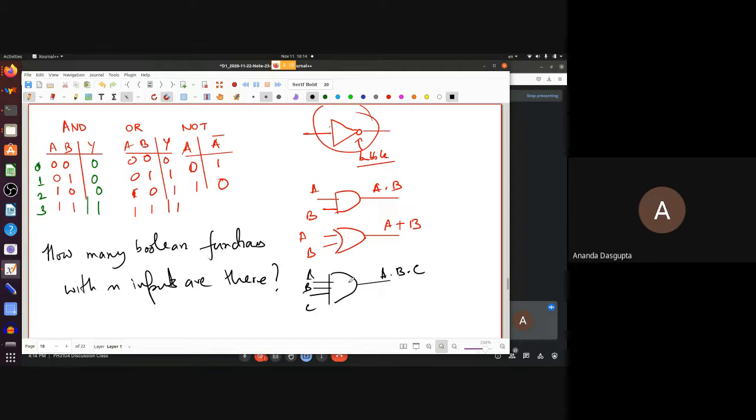The answer to that, of course, can't be 0 because you can see 2 of them right now in front of your eyes, right? There's an AND and there's an OR. Both of them are 2 input gates. And they're different, right? Different functions. I'm going to interchangeably use the names gates and functions, although at a mathematical level, we are really talking of a function which takes in 2 inputs and produces an output. A gate typically is a physical realization of that, a physical circuit which essentially does the same job that the function really says. So a physical circuit which will produce a high output only when both inputs are high and low otherwise, that's an AND gate. The AND function is a mathematical function. It's just a function which returns 1 when both inputs are 1. But we are going to use those words interchangeably. So, how many two-input Boolean functions?